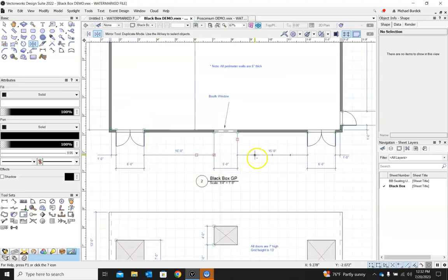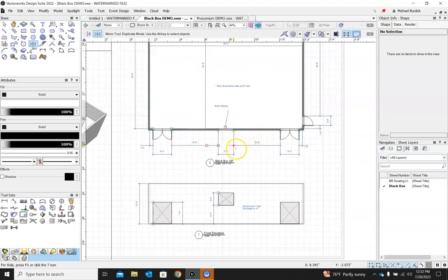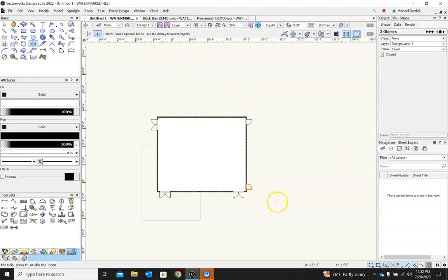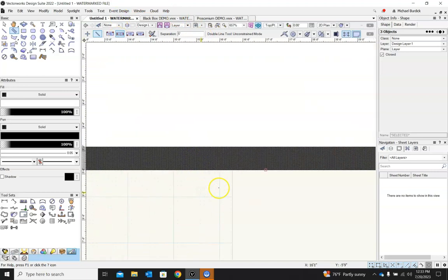That, it looks like 15 foot, is centered right on this back wall. And it's 5 foot wide. So, with snapping enabled, we'll be able to snap right to the center of that wall. I'm going to go back to my double line, and I'll use center control line, because I know I'm going to be able to place this right on the center and just draw. Instead of 6 inches, I'm going to make this 5 foot wide. So you'll see here, if I click on the center, and when I hit it, it'll lock in and it'll say bottom center. Then I just draw down,